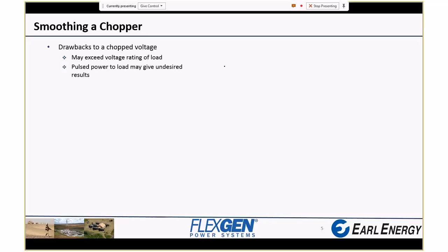We were pulsing a voltage to the load, so we can redraw the circuit: battery again, our switch, and we put this capacitor right across the load. We think this capacitor will help resist the change in voltage that we were applying by pulsing the voltage to the load.